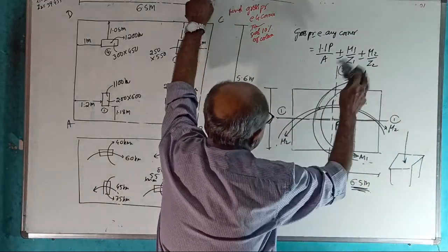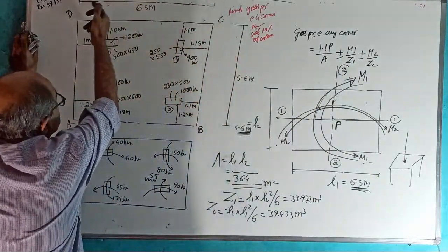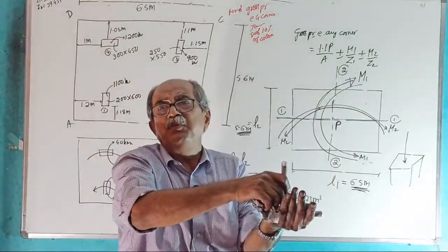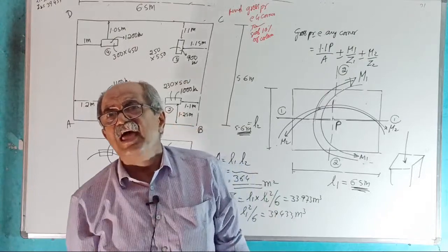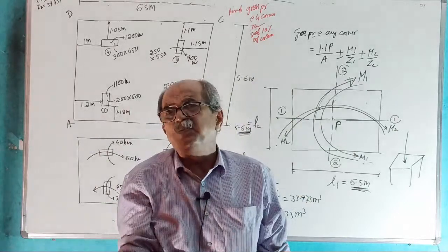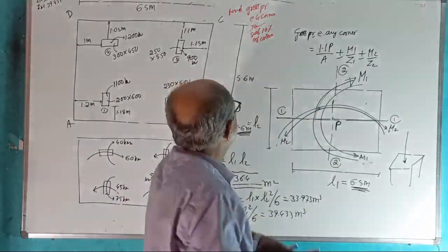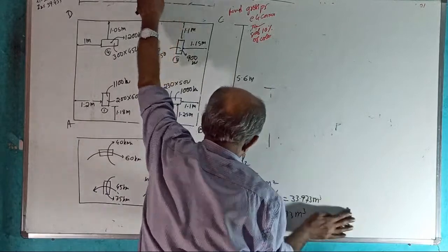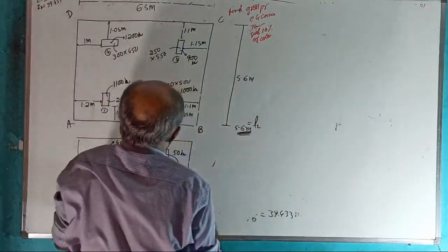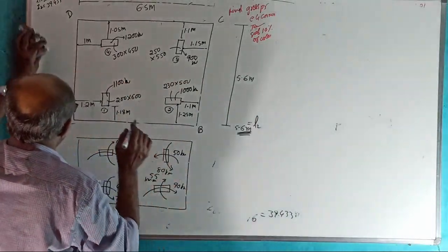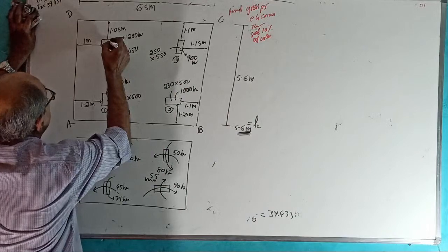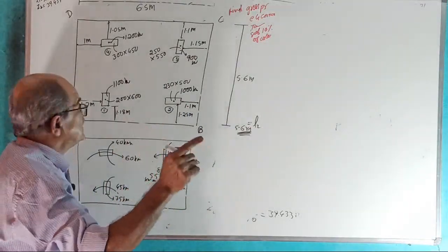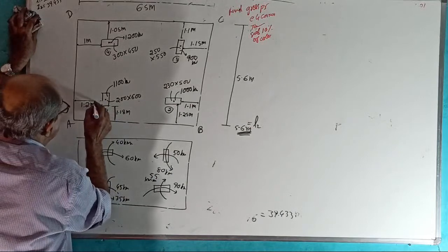Now remember, we want to replace this complete system by a single force P through the CG of the footing, along with a single lengthwise moment, this way or this way, and one moment like this. Now L1, L2 are not required for me, none of them, so I will remove everything. This is required. Now see, you have the distances. One column load here, one here, one here, one here. You write one more sketch where you mark distances to the center of the column.